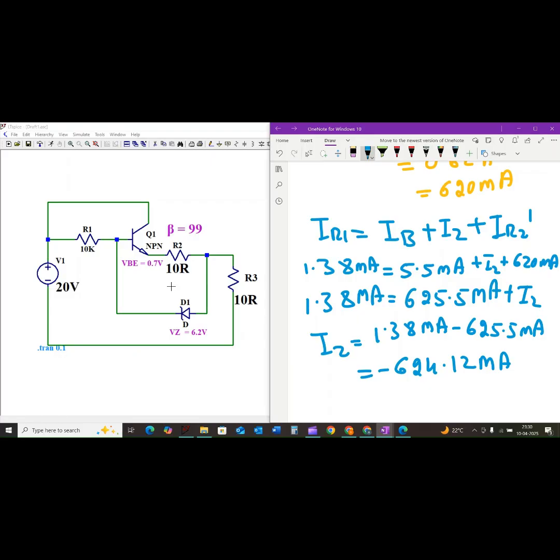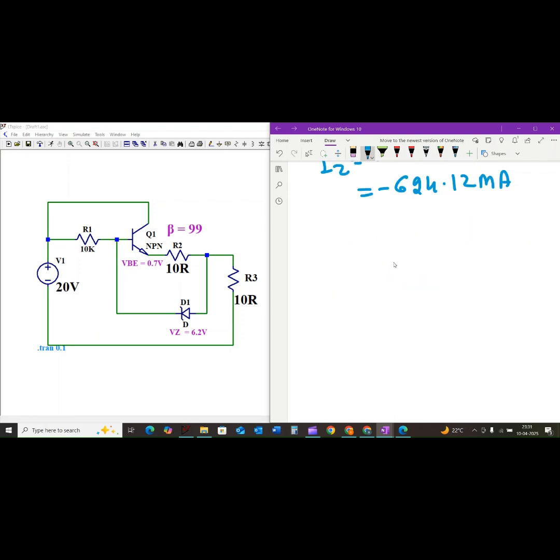The voltage at base is not high enough to put the Zener diode into breakdown, while also satisfying the transistor operating condition. So, what's really happening here? The transistor is likely operating in active region and the base voltage is determined by the voltage divider action involving the resistor R1 and the input impedance of the transistor base.